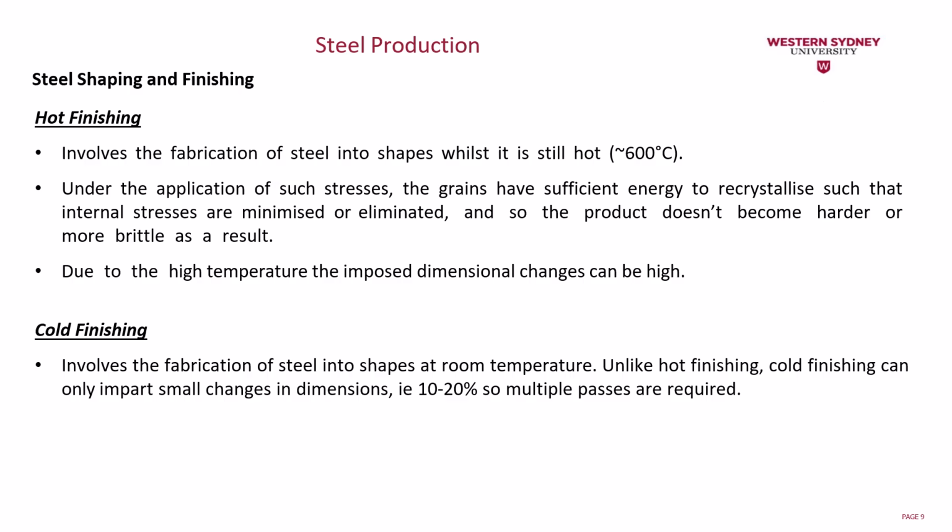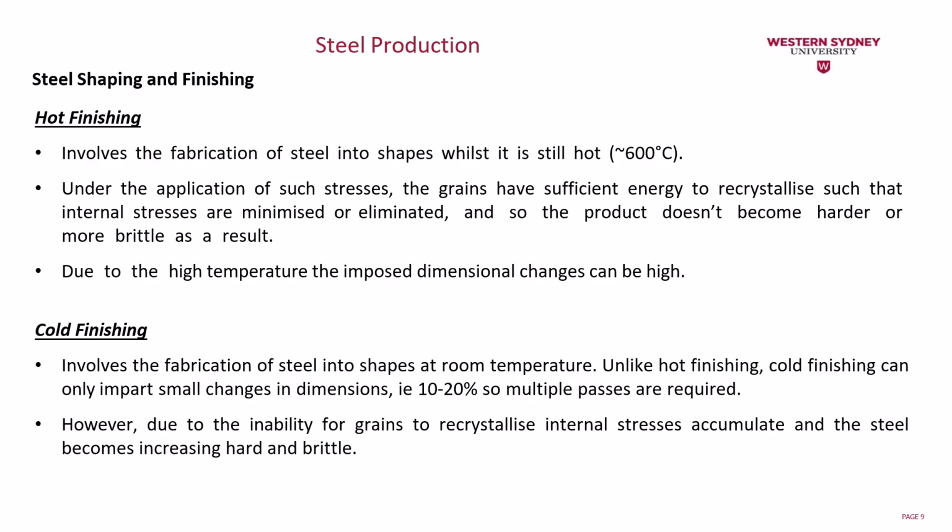So if I have a plate with 5 millimeter thickness and I want to roll it to 1 millimeter thickness, I may have to do it over 3 or 4 steps in the cold forming or cold finishing, while in the hot finishing maybe 2 steps is going to be enough, and sometimes even 1.